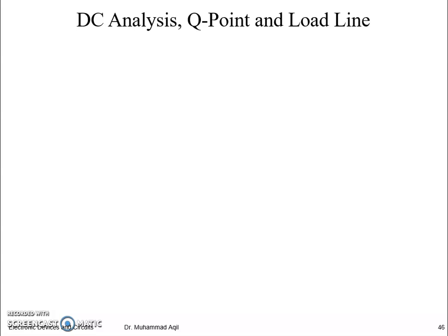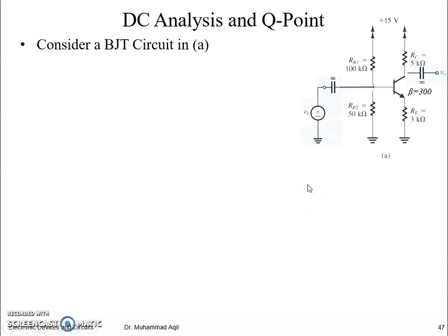On-off switching and amplification are the common applications, and the most common one is amplification. So we have selected amplification as an application to be studied in this lecture. This is a basic circuit of an amplifier in which you can see the input AC signal Vi being injected through this capacitor into the amplifier, and the amplified output, that is Vout, is being taken out through this capacitor.